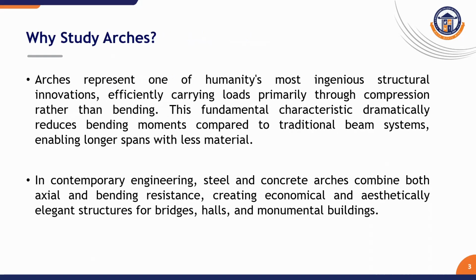Why do we have to study the arch? Why are arches so important in structural engineering? Because they significantly reduce the bending moments, they are economical for long spans, and they provide an aesthetic appearance. Modern arches in steel and RCC resist both axial force and bending, making them ideal for bridges, auditoriums, and industrial sheds.